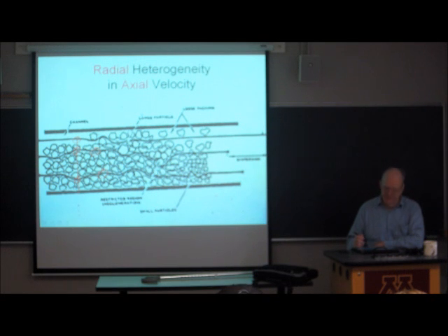To a first approximation, this radial heterogeneity in the axial velocity is what's responsible for the A term. This process has a lot of different names. It depends on which literature you're reading. The most common name you'll see for it is eddy dispersion